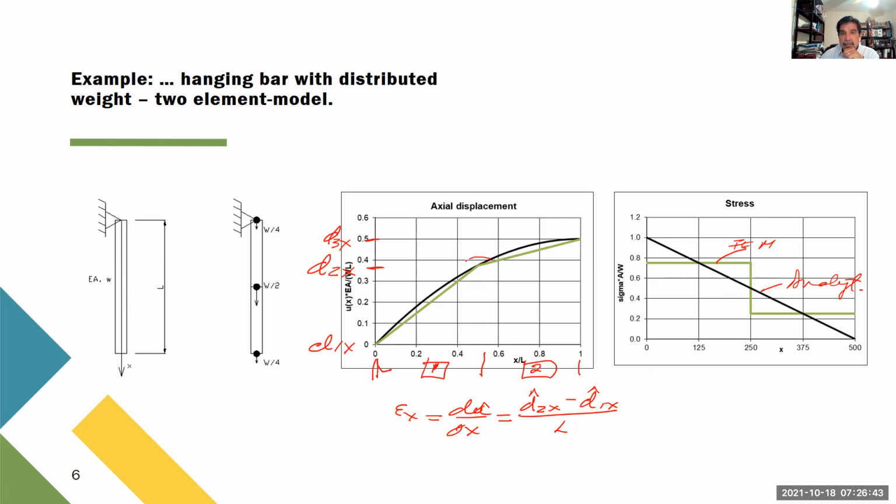So we see that the displacements are exact. The distribution of stress is not. Okay? This is exact because when we replace the weight of this, because this is uniform, into this, it is statically equivalent. That's why we get the exact values of the displacements. But in between, no, we have an error. Okay, so we have to be alert on that.